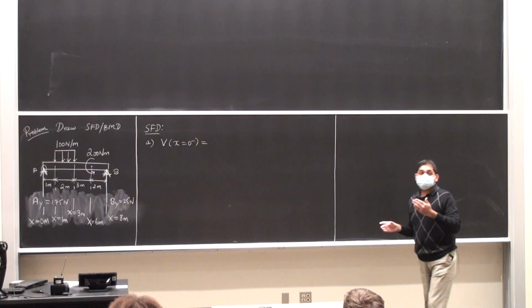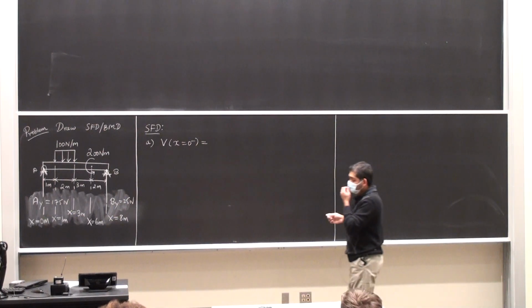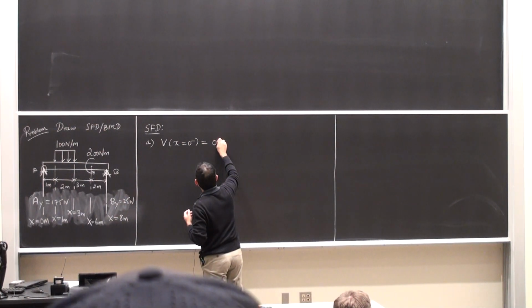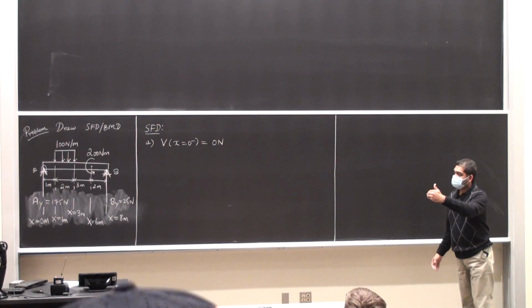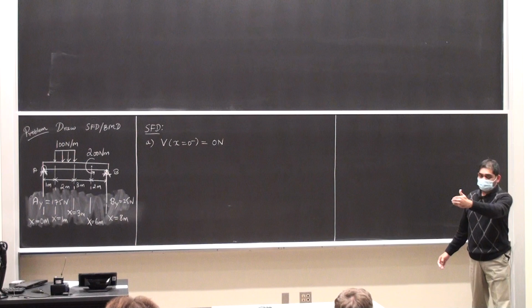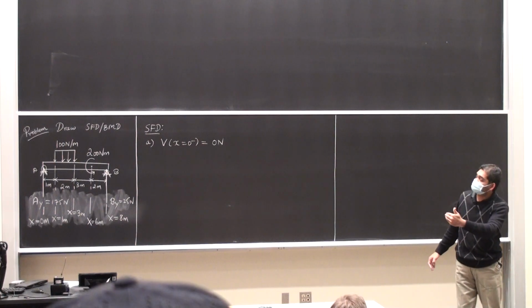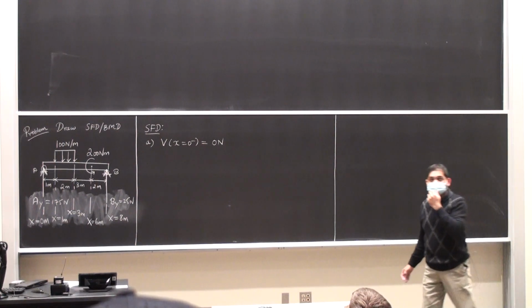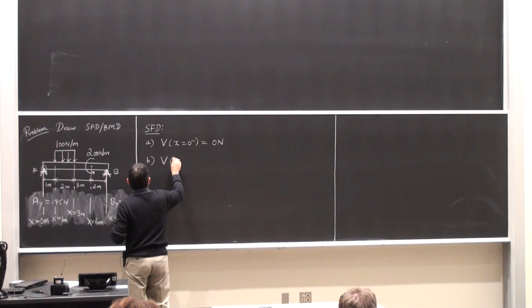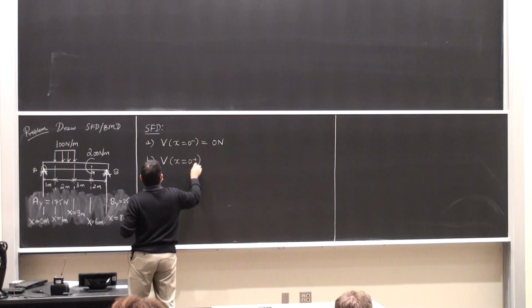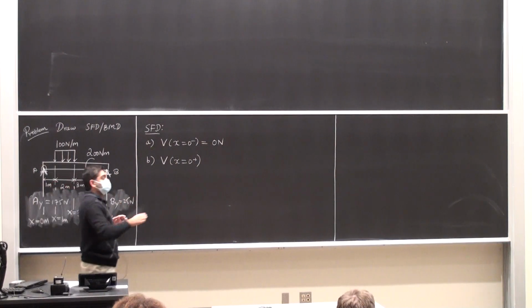This is always going to be starting at 0. Okay, so 0 newtons because there is no beam at 0 minus. Then I go to x is 0 plus, which means this is right after the force Ay is acting. So V at x equals 0 plus minus the change in the shear.